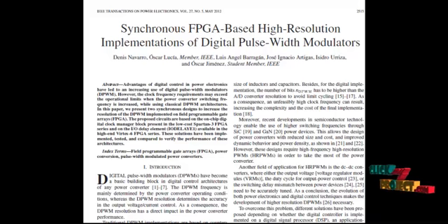In our work, we propose a new hybrid digital pulse width modulation architecture. The synchronous block is counter based. However, the asynchronous block is not based on building a new delay line structure, but uses the field programmable gate array's available clock loops. This is the main difference from previous solutions, which developed their own delay lines or DLL.